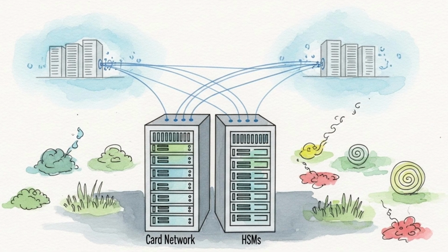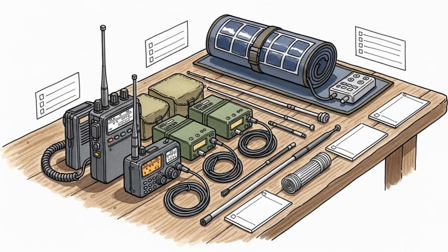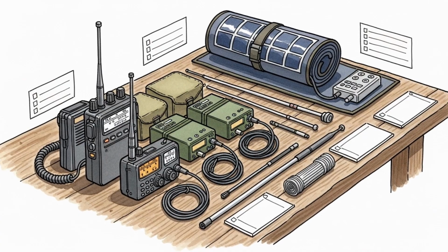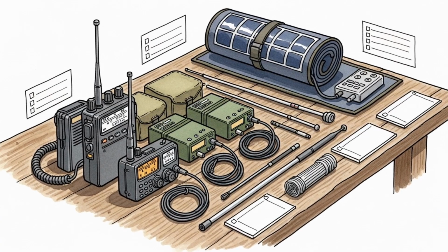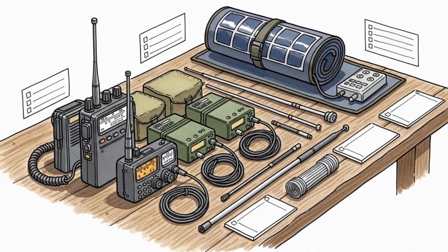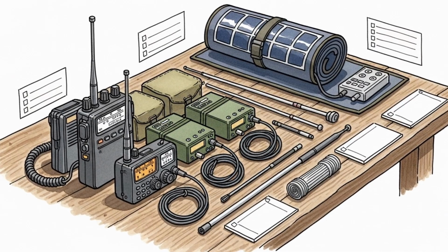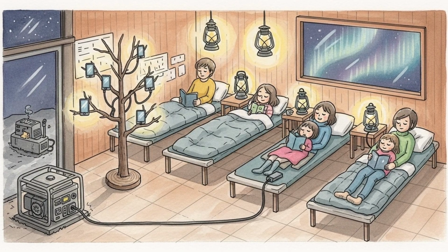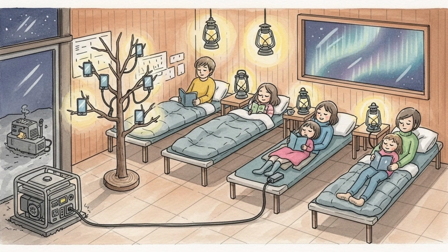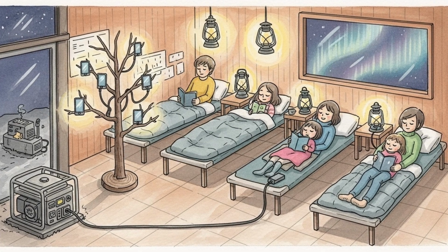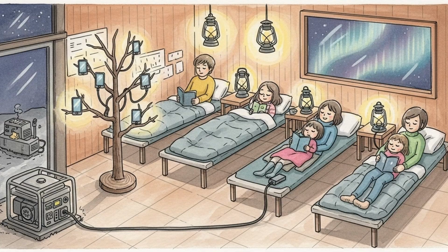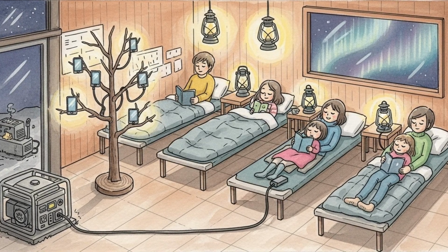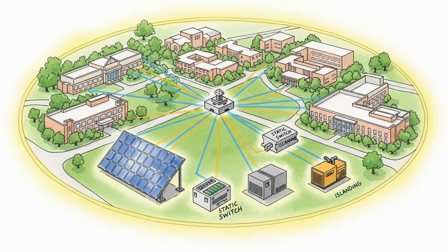Part 6. Satellites, orbits, and navigation. Space weather disturbs satellites in three main ways. First, it changes the radiation environment and raises the rate of electronic upsets. Second, it increases the density of the upper atmosphere and adds drag to low Earth orbit. Third, it makes the ionosphere irregular and degrades radio propagation and navigation signals. Each effect has clear operational consequences for attitude control, power, communications, orbit prediction, collision avoidance, and user positioning and timing